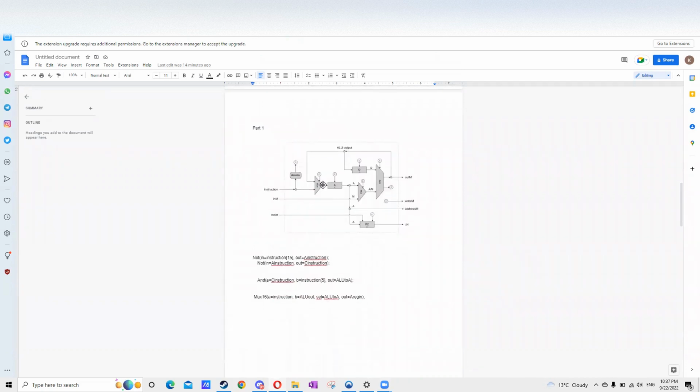I covered a bit of what we just said, but I'll go into more detail with this one. So the CPU abstraction and the CPU API, we talked about that. Now we'll go back to the CPU diagram and see how everything works. The ALU will give an output right here that can be written to the data memory. To do that, the CPU must confirm what is going to be written into the data memory, and the value of that will be stored inside outM right here.